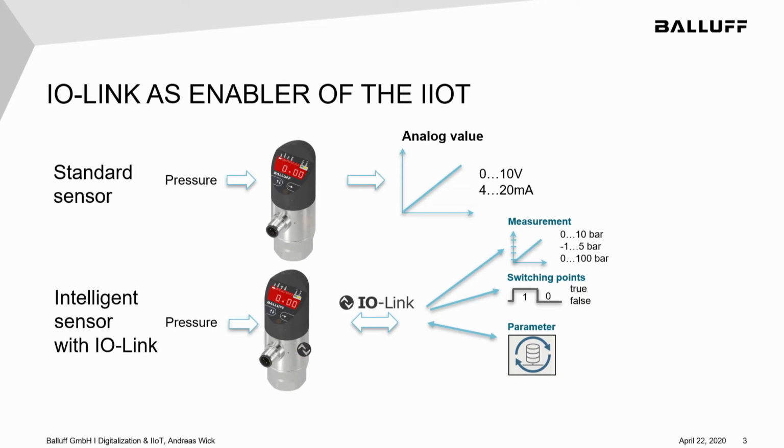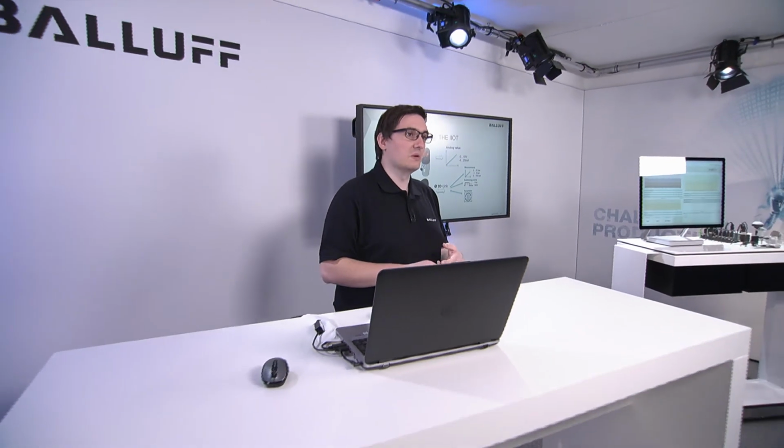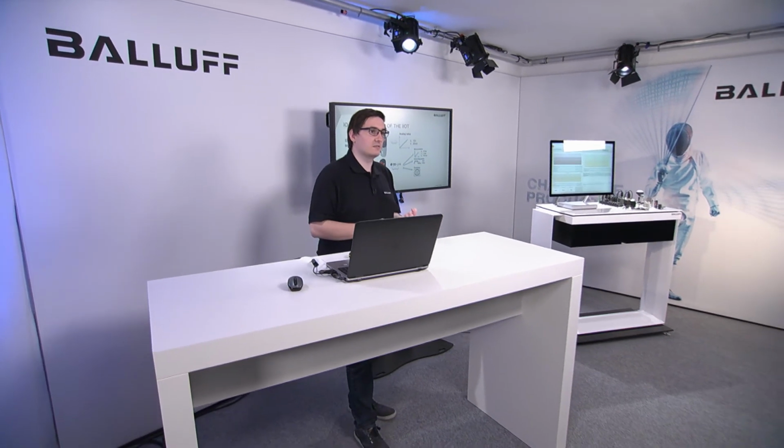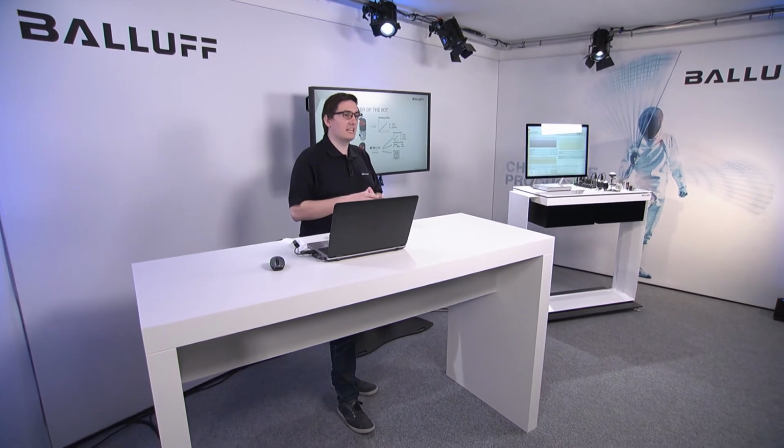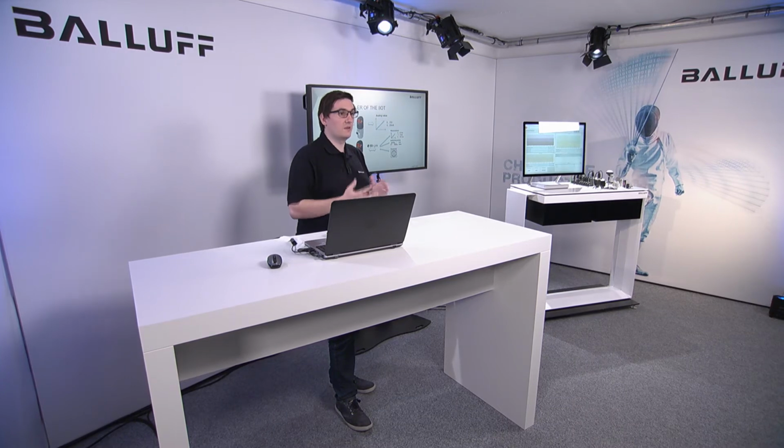The parameters I want to talk about, though, are the ones the sensor provides for reading. This means additional data like internal device temperatures, operating hours, boot cycle counters, excess gain values, and raw data values that you can use for further analysis.